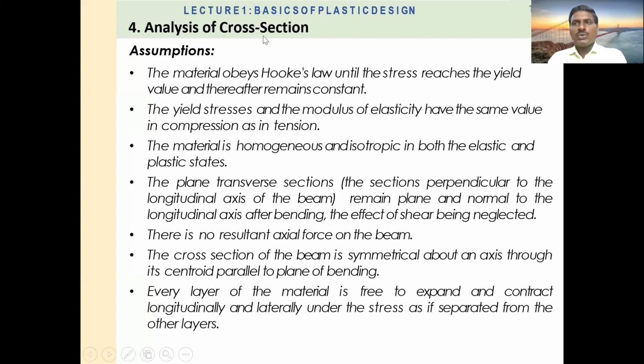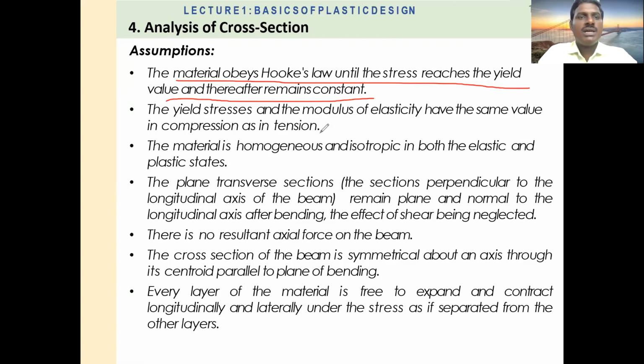So now, in plastic analysis, there are many assumptions. What are these assumptions? The material obeys Hooke's law until the stress reaches the yield value, and thereafter remains constant. What is the first assumption we have to consider? That the material obeys Hooke's law. Hooke's law is nothing but stress is directly proportional to strain. It means that is the elastic condition. So that is the first assumption we have to keep in mind.